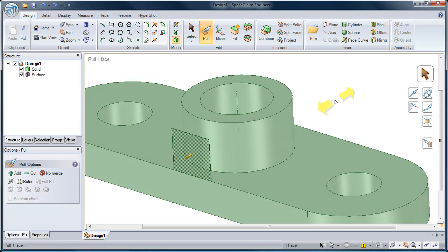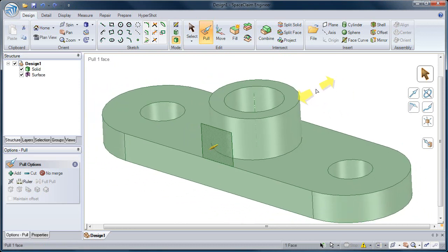We might want to undo again, and this time, I'll use one of the tool guides. Tool guides on the right side of the screen will change the function of your tool slightly. So, for example, letting you draft geometry, or sweep geometry, or rotate geometry. One of the tool guides I use most often is the up to button.